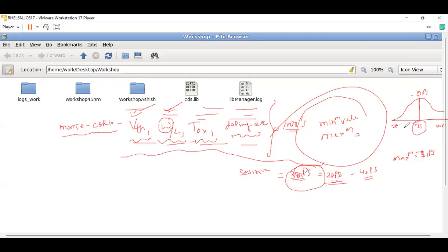It is used in Cadence Virtuoso, where you will read two words. It gives you either a global mismatch or local mismatch. Now, what are these two terms? These are less used in digital VLSI, but these terms are mostly used in analog VLSI design. But you should know the difference.